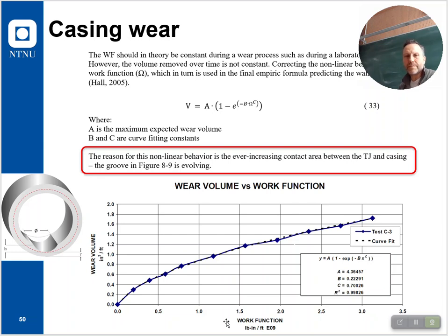We see this type of wear, a wear groove, a crescent type ball loss. And that means that at some point there is a point load type contact. The drill pipe tool joint, specifically the hard banding on the tool joint, would rest on the inside of the casing, and the wear would be very high because the force is the same, but the pressure changes because of the contact area, right?